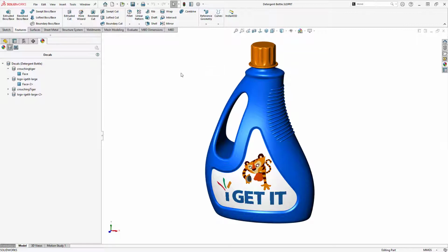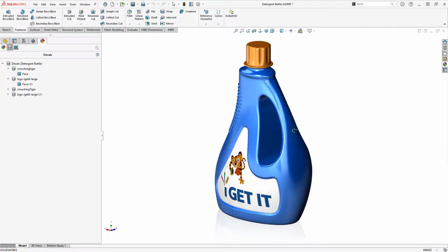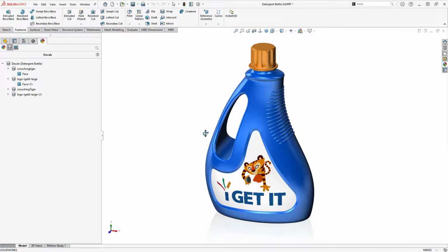So the next step is you can go into the view settings drop down here and apply a few different things to change the way your model looks. The first option here is real view graphics. If you're familiar with it, it just adds some lighting and some surface complexity to your materials and makes things look a little bit more realistic, and depending on the settings you have associated with it, can have ground reflections and all kinds of different more realistic looking things.